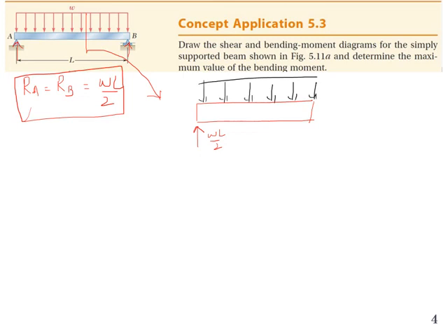And we have a shear force and a bending moment, again following the sign convention. Now this distributed load we can change into a concentrated load, and that is W times X, as you know, where this distance we take as X. Now we took a section, and let's call this section C over here.